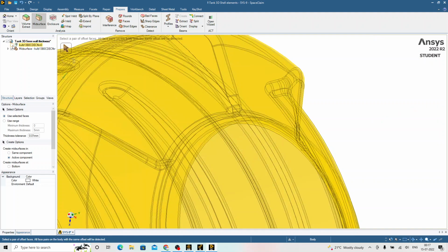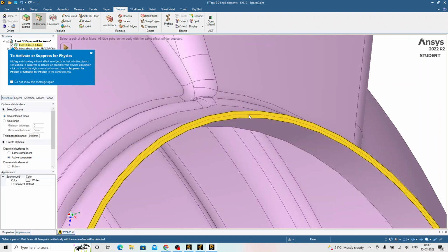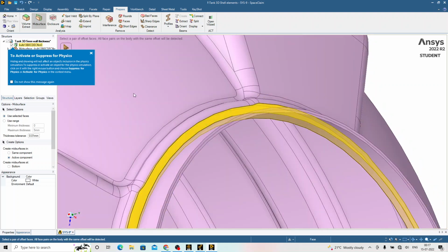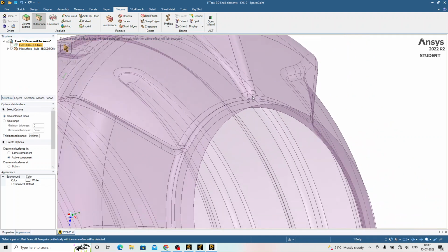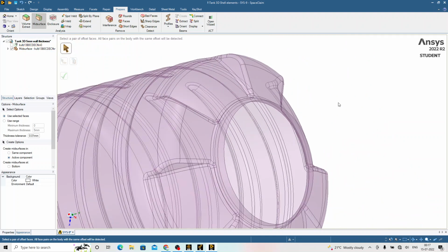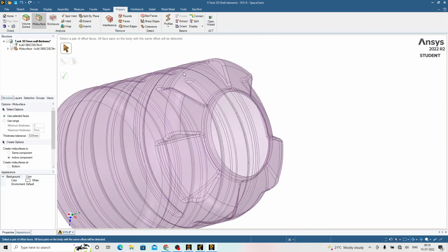Now if we just switch on this body, we can see one small line, the center line. This is the mid surface for this uniform wall thickness 3D body. We'll switch off that. The body also is suppressed. We are not going to take the 3D for further analysis. The 3D body is suppressed and hidden. Only this surface body will be taken care of.